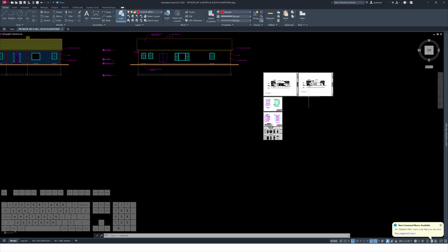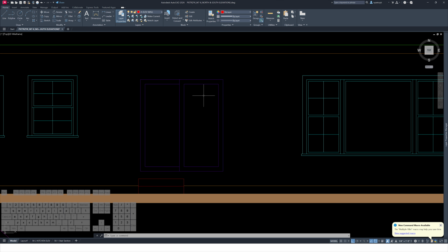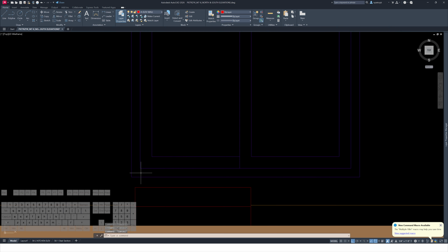So fine. Anyways, I also need to do a 3-inch offset around the door, except for the bottom. Make current. Except for the bottom. I'm literally gonna do the exact same thing that we did with the windows, but an offset of 1.5 inches, lengthen DE of 1 inch.